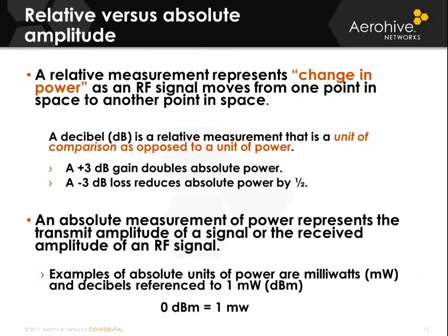Relative versus absolute amplitude. A relative measurement represents change. What is changed here? What's different? As an RF signal moves from one point to another, there is going to be a change in that signal strength. It's much stronger near the transmitter and weaker as you get farther away. Remember, a decibel is a relative measurement that is a unit of comparison as opposed to a power unit.